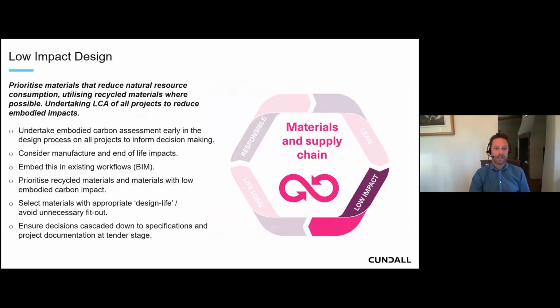So, low impact: really starting to focus on the impact of those materials, embodied impact particularly. That means looking at embodied carbon and carrying out embodied carbon assessments early in the design process, at your very conceptual stage, looking at the impact of different solutions through the whole life cycle, from manufacture to end of life, and embedding this in your workflow so it doesn't become a bolt-on, it just becomes part of your day-to-day practice.